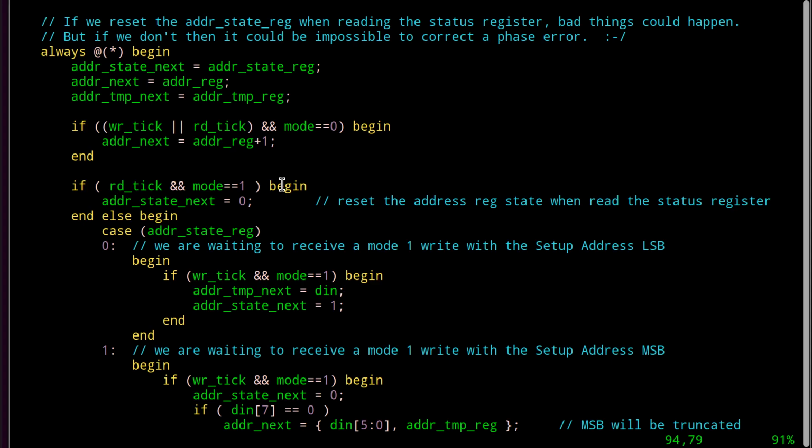So, the short of it is, I usually don't enable interrupts when I mess with this thing. You can, but you need to make real sure that when you're accessing the VRAM, you do it after an interrupt occurs and get all your work done before the next interrupt occurs. And you can do that by timing your code and just being careful, which is, to me, a really crappy thing to have to do. But it's the era that we were in, and I think it was short-sighted. It's probably a design flaw in the chip.